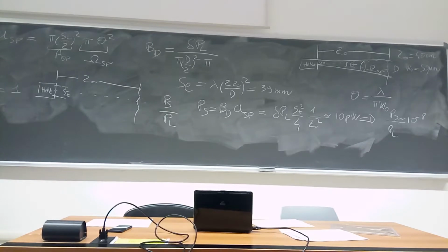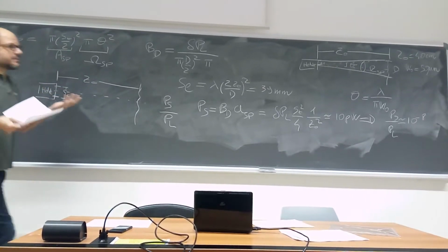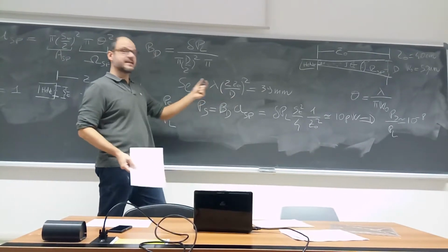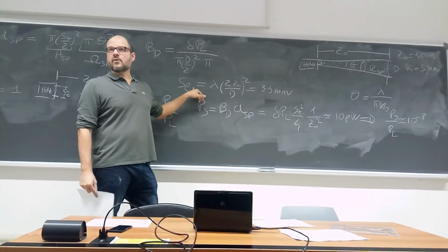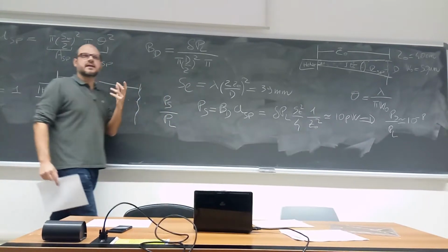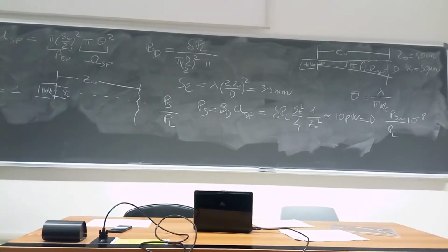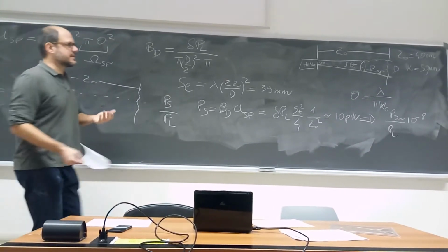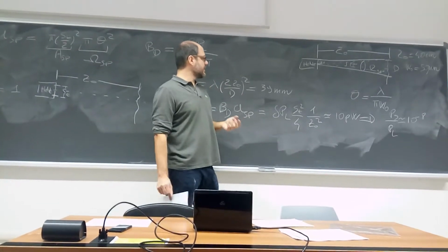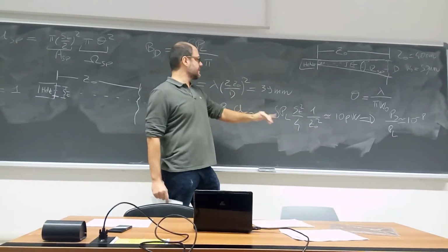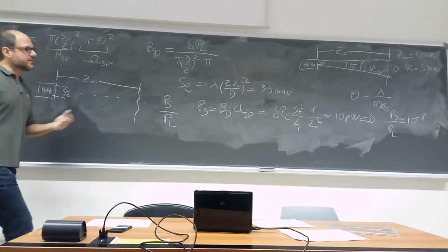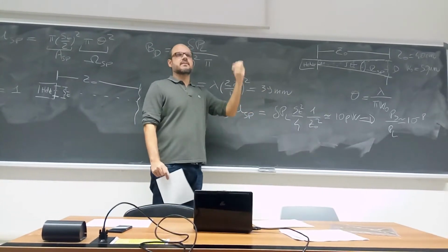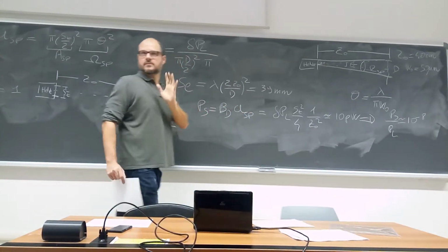So we can also look at this information in a good way, because of course we know that we must limit the dynamic range to a quantity that is much lower than this quantity. But since now we are using the interferometer like a vibrometer, we are measuring vibration of a target. Vibrations are usually, let's say, hundreds of microns, some millimeters. This is 39 millimeters. It is good. It's not bad, because this quantity is definitely larger than some millimeters of vibration.